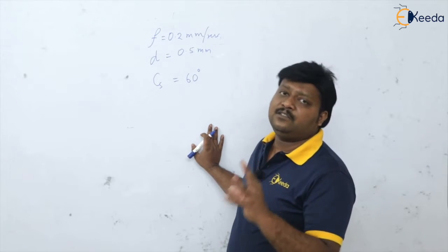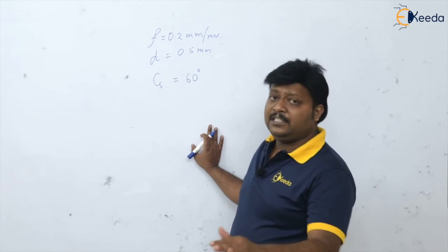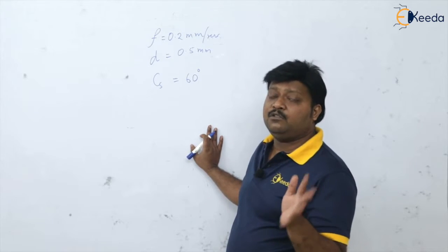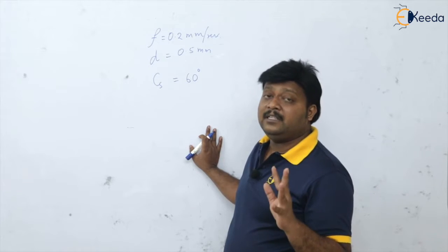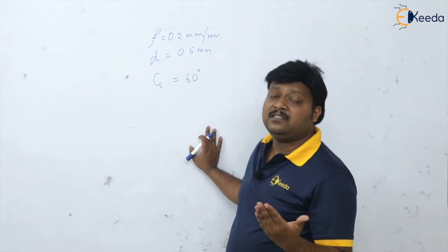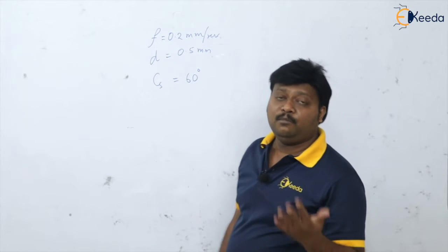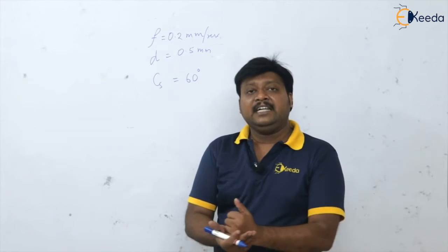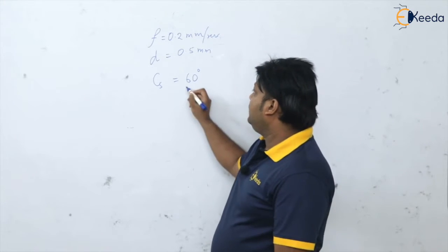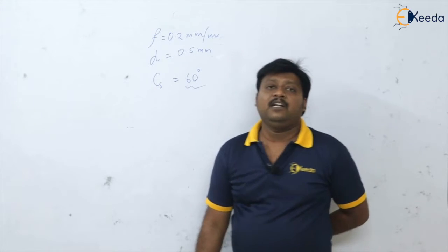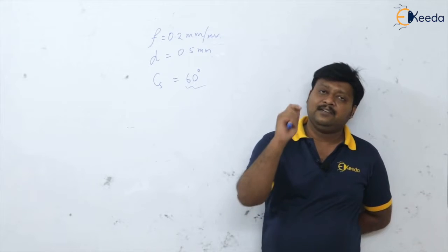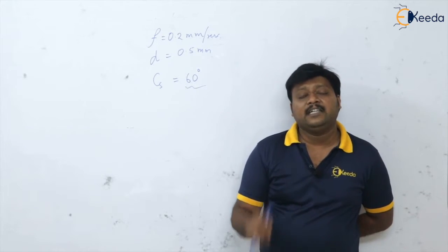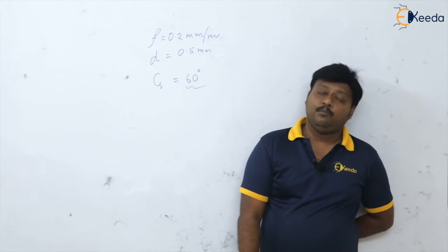In this question nothing is mentioned about whether this is orthogonal. Please remember, there is always the maximum chance that the question is from oblique cutting. And it is 100% confirmed when in the numerical they provide the value of side cutting edge angle or the principal cutting edge angle, then of course the question is 110% from oblique cutting.